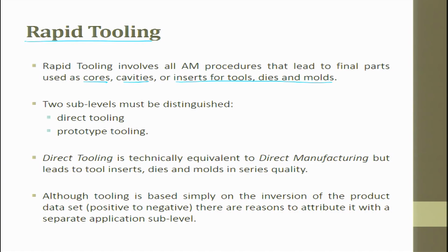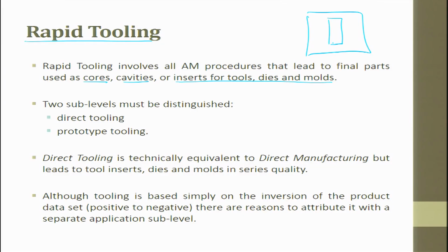You put a core so that you have a closed cavity, and here you do not want material. So, you put it as a core. This core cannot stand freely in air, so you put supporting elements to hold the core, and now this portion will be made of the material. Okay. So, this can be used for casting or molding.